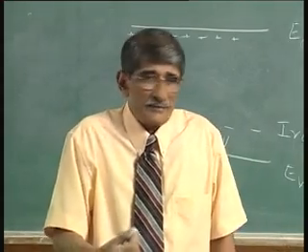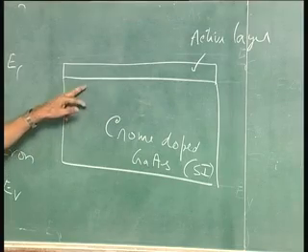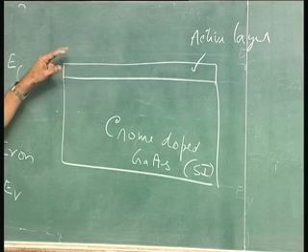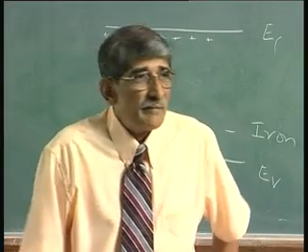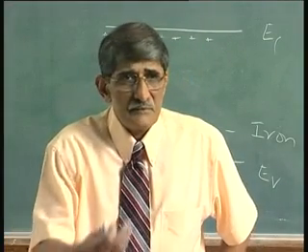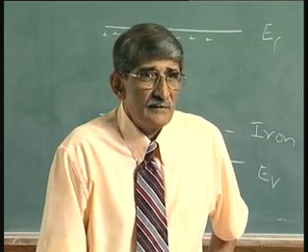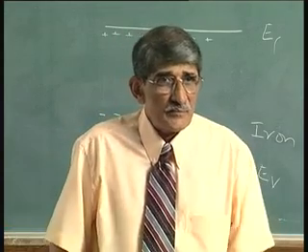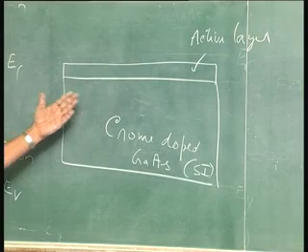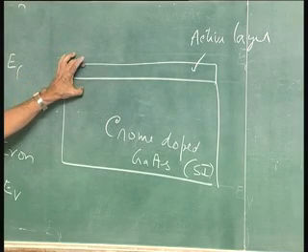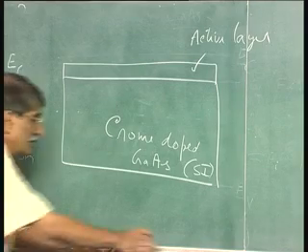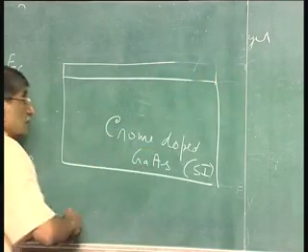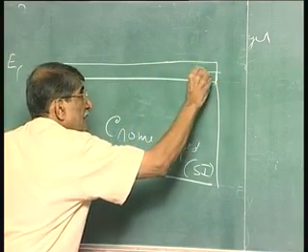All these deep impurities which are added deliberately, they can diffuse. It gets into this. Once it gets into this, the properties of the layer which are growing changes. That was one of the major problems people had when they were making the gallium arsenide devices, 1980s. But after that, the problem has been sorted out without adding chromium. So, in this case, what they were doing was, don't put the active layer right here. What do? Put a buffer. So, solution is put a buffer layer.